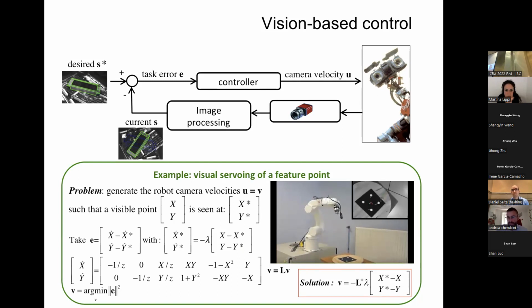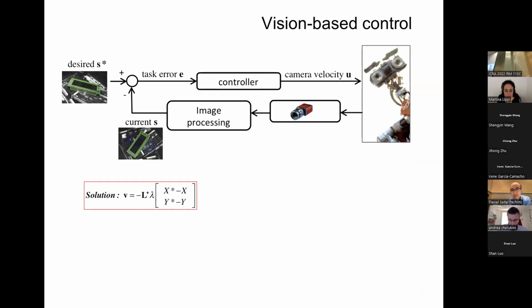And this framework has been very popular lately. It's also called visual servoing. So if we go back to the equation, we have 2 big issues here when we attempt to apply it to soft objects. The first one is that the task is very highly dimensioned, because the soft object has many features, possibly even infinite features. So you cannot just rely on 2 as in this example, and very quickly this leads to an underactuated problem, since our robots often have 6 or 12 degrees of freedom.